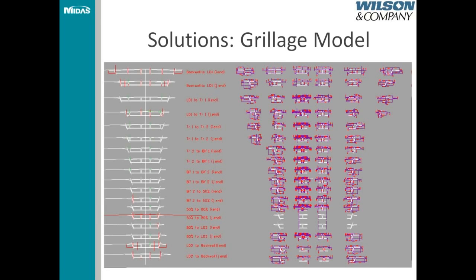This is a screenshot of the drawing in MicroStation. Up at the top was the plan view of the structure. I used that to bring straight lines down to mark the locations of the webs at the top of the deck. And from there, I could use the typical sections to draw out the rest of this cross-section.